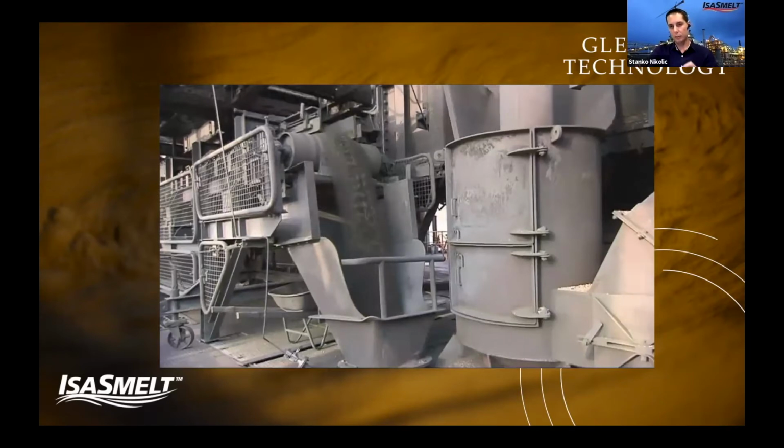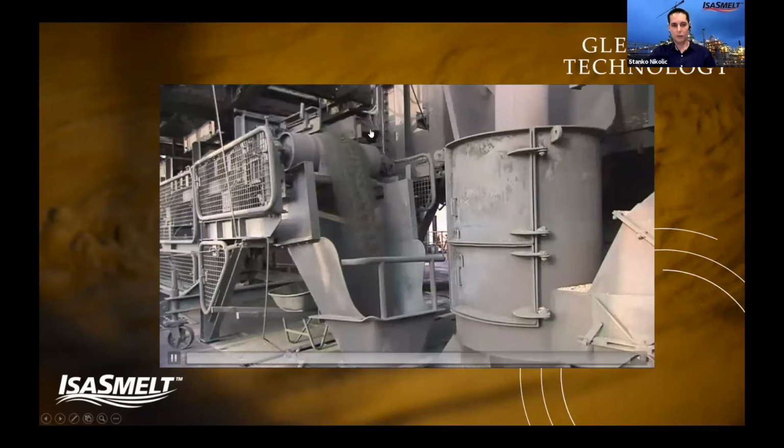So it's an ability to, one, look at the operation of the furnace, but also look at the longer term trends of where you want to run the furnace, where you want to be. You can see here on this image our final feed device, putting the concentrate down into the roof port of the furnace. Just for everyone's interest, what is this thing moving back and forth here at the top of the image? That's actually the ISASMELT lance that's providing the air and oxygen to agitate the bath of the furnace itself and to drive the smelting reactions through the turbulence of the bath.